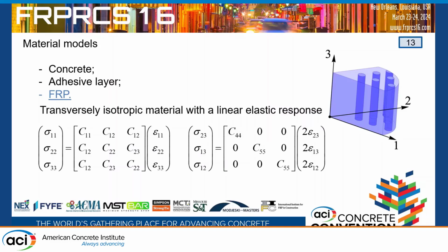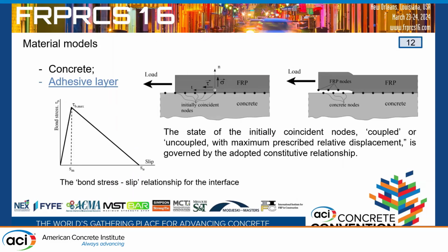Thank you. What did you use for your adhesion layer? So for the time being, it is only this. Maybe it would be better to model the adhesive layer with slip, because if you're pulling out the concrete, that means you've got too much adhesion at that point. Here we are making the assumption that if you have opening, this is the concrete which fails, and if you have shear, this is the adhesive which fails.